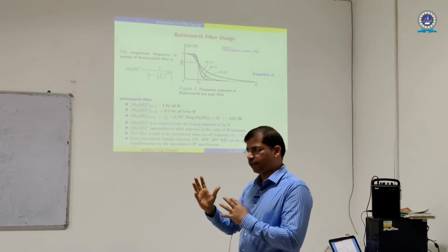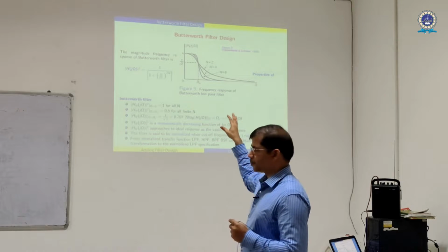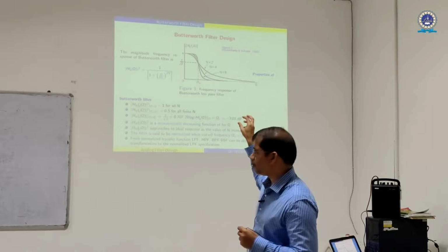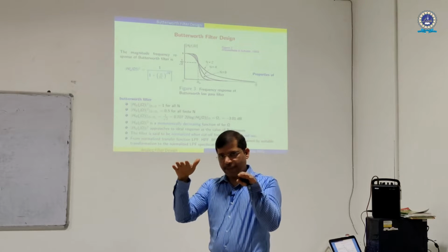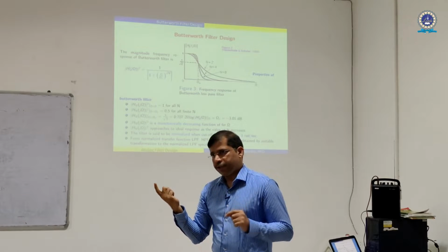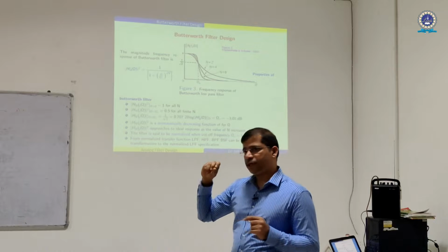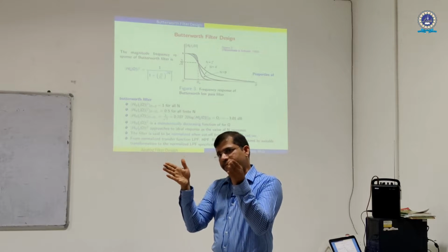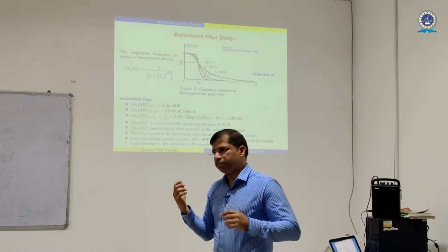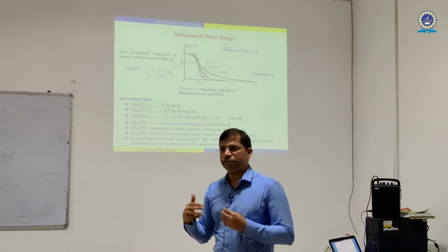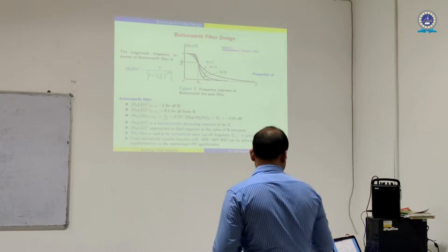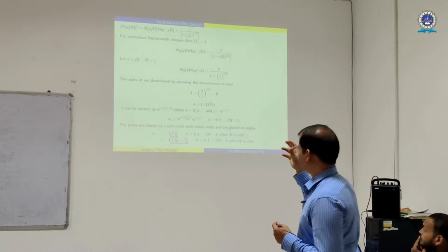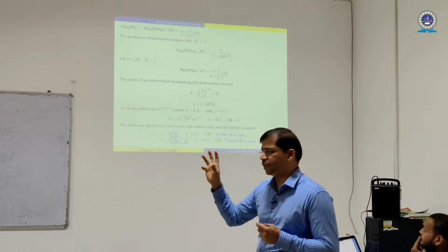So in some other way, for that particular equation we are getting this. If you look at that equation, there are fewer ripples in the magnitude in the pass band. But if you look at the Chebyshev, where the entire equation is expressed in terms of hyperbolic functions of cos, you get more ripples in the same pass band. So that's why we thought Chebyshev is better than Butterworth. Right. So this is a small fundamental thing, how we have to design the poles.